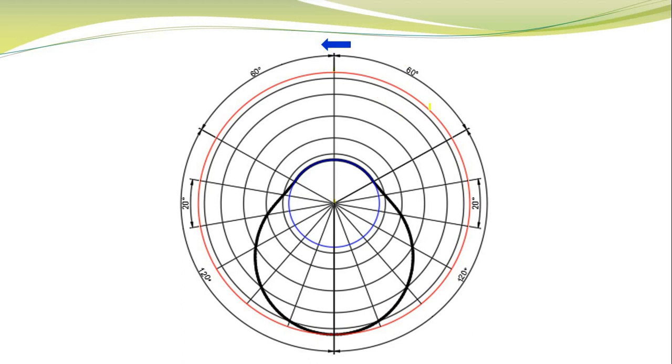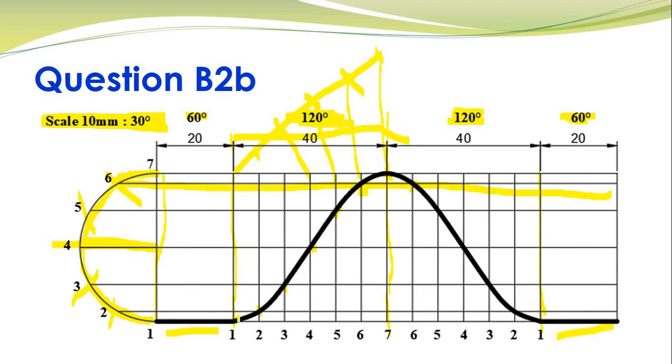So what happens is, between this maximum stroke circle and your minimum cam radius, this is very important, because between these two circles you will have your cam profile. Now, the manner in which I will draw my cam profile is, again, the first thing is you need to divide this into the 4 blocks, and those 4 blocks are with respect to what we did over here.